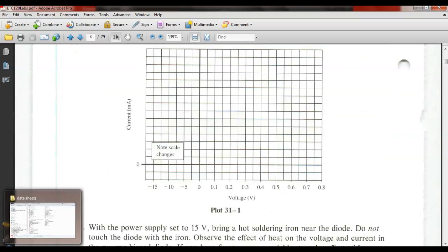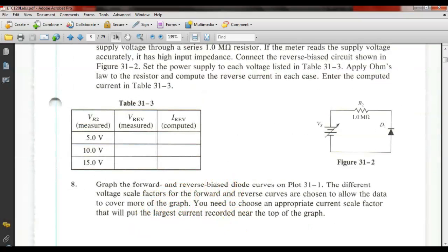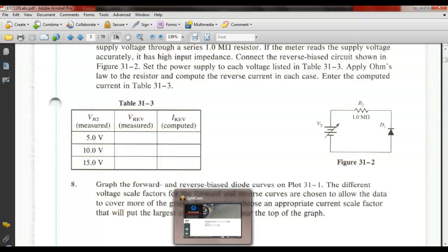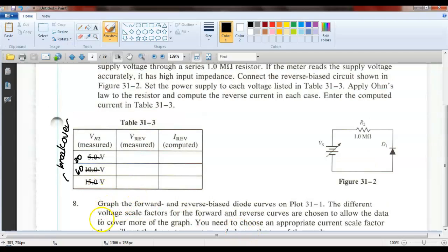Okay. So this toggle right here I'm going to do, so notice this guy's reverse bias. We're protecting this with a 1 mega ohm resistor. So we're going to watch this real careful. We're going to measure across the 1 meg. We're going to use, let's see what I have mine set up for. So you need to mark yours out. We'll go 30, 60, and then wherever it breaks over at.